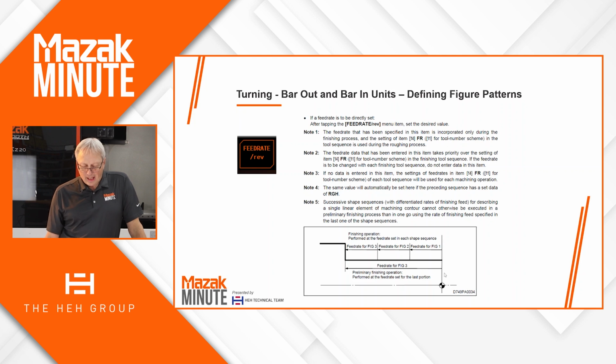If you had one line segment that had broken up into maybe multiple micro finishes, you can program each, even though it has the same X, I can program the Z surface at different ones, and go ahead and put in a different micro finish for those sections.